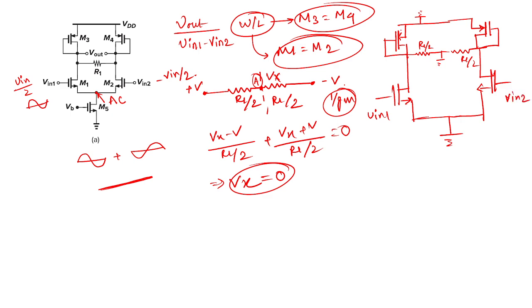And you can see the whole circuit is symmetric with respect to this axis. So calculating the overall differential gain of this circuit and calculating the gain of a single side will give us the same result. So we do not need to calculate the gain of the overall circuit. You can just replace the circuit like this.